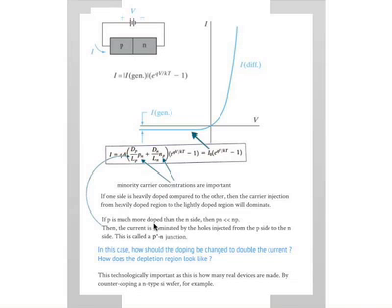Those are the basic ideas, and this is where we stopped. The current characteristics are shown here: that's the current, that's the voltage. You have a very characteristic curve. The key point to remember is that this constant term in the front is also called a generation current because it comes from the electron and hole injection. It's a minority carrier current.